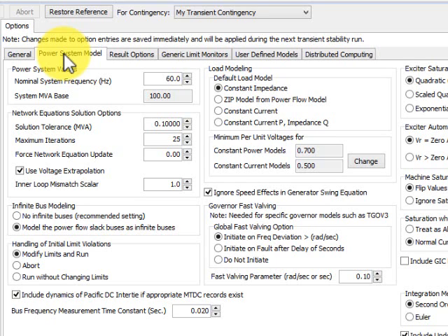Yeah, so this is new because you had to check something in order to have it follow this. The way I'm interpreting this now is it's going to follow it even for the composite load model, which, for static loads, often has a small constant MVA component, and so I think we want a choice whether to have this applied or not. And the way I interpret this is we don't have a choice. We have to specify a voltage sensitive threshold for the constant MVA model. Unless you put zero, then it goes. Unless you put zero. Yeah, I mean, you can change these values.